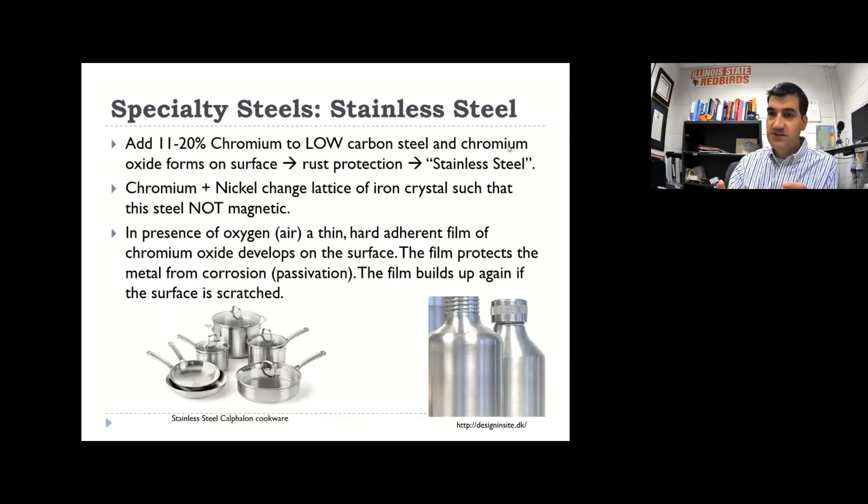It's just the outer layer of the material that actually oxidizes and forms chromium oxide, but that's called a passivation layer, otherwise known as a passive oxidation layer, and it actually protects the material underneath it so that it does not oxidize. And it's all about the chromium oxide remaining a part of the lattice structure of the steel.